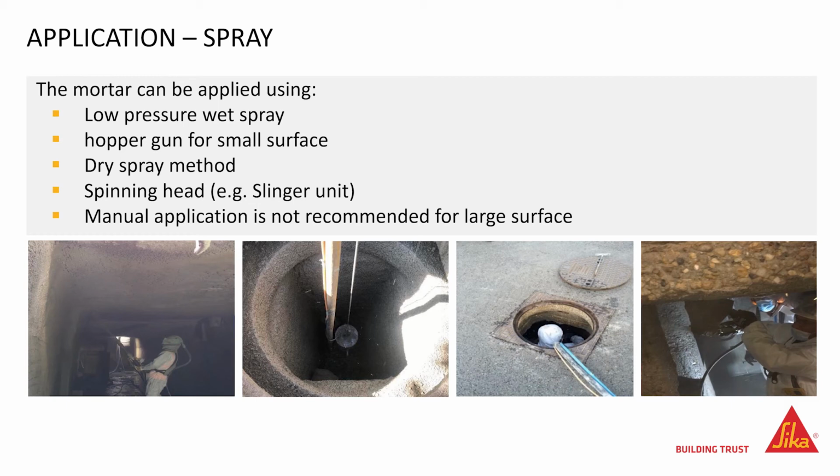The third picture was taken in manholes renovated in the Netherlands. We can barely see the operator applying the mortar using the wet spray technique. And finally, the fourth picture was taken in a project in France, and for a small area, the applicator has used a hopper gun to place the mortar.